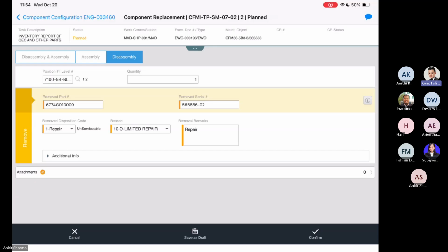For the module, you have a configuration. Now, you physically validate those sub-assemblies. Then once again, you go for the next level of test. So this is an iterative process, right? Your inspection and disassembly go on until the stage where you've completely torn down your engine, or to the level which you want for that particular work scope.